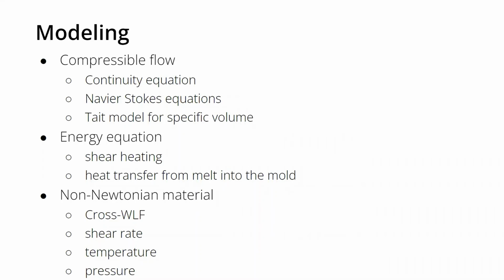So the fluid flow is a multiphase flow. It is compressible. The equation of state is a very complex polymeric model, the so-called Tate model. In the energy equation, you have shear heating, heat transfer from melt into the mold, and you have a non-Newtonian fluid. So it is a very complex phenomenon. And I was very happy that the simulation worked and